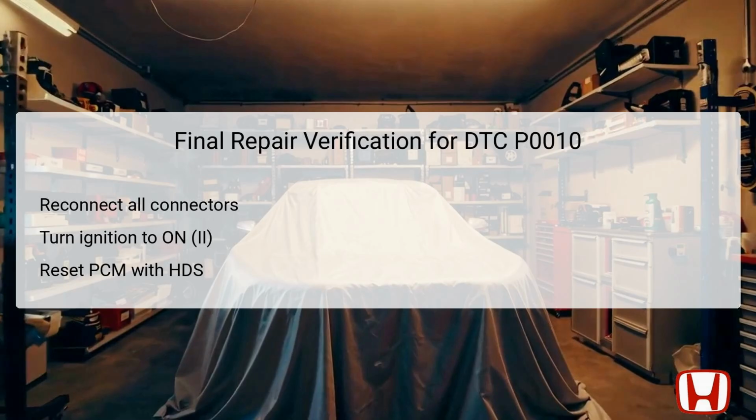Utilize the HDS to reset the PCM, effectively clearing any stored diagnostic trouble codes and preparing the vehicle for a fresh test cycle. After resetting, the system needs to undergo the PCM idle learn procedure, allowing the PCM to recalibrate its learning parameters for optimum performance. Then, conduct the VTC test from the HDS's inspection menu to verify that the VTC oil control solenoid valve is functioning properly and that no faults are present. This step ensures the engine is operating within specification, finalizing the troubleshooting process.